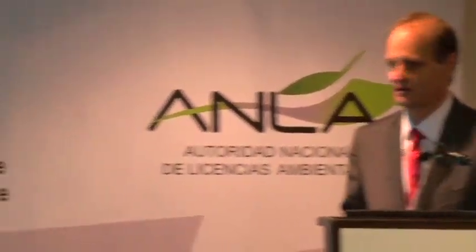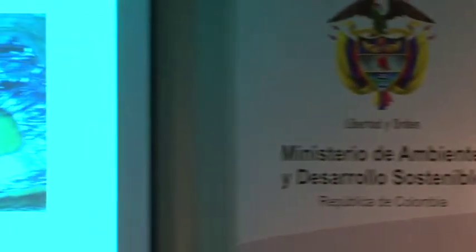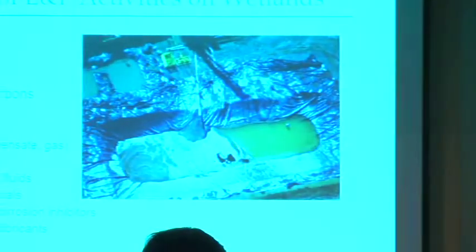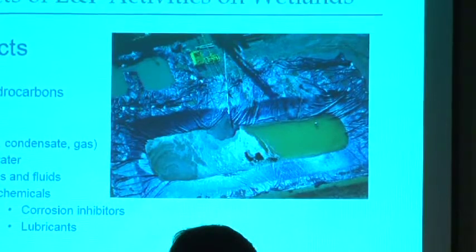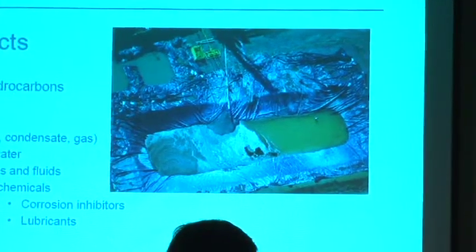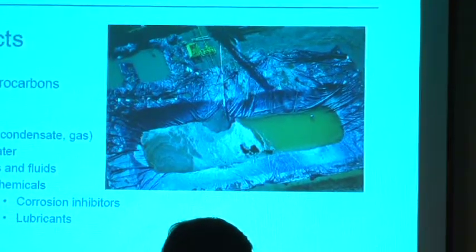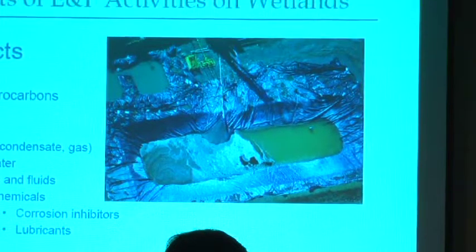And you can see that the pit is not only placed in an area, but it's lined. It's lined with an impervious liner, because we don't want any of that stuff to get out into the groundwater. So the good management of how you're going to handle that. And again, in certain situations, that material is not placed in a pit, it's placed in a tank. And those tanks regulate the water and dewatering of the material inside.